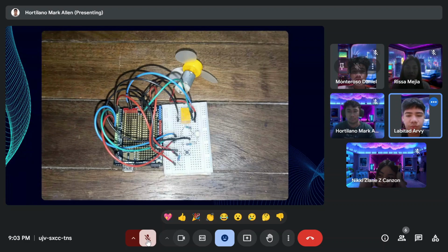Connect the common pin, cathode for common cathode RGB LEDs or anode for common anode RGB LEDs, to GND for the common cathode type or 5V for the common anode type. The code assumes a common cathode type LED where each color is controlled by grounding each pin. Adjust the code for a common anode type by inverting the PWM values for each color. And for the power supply, use the Arduino's 5V and GND pins to power the circuit.